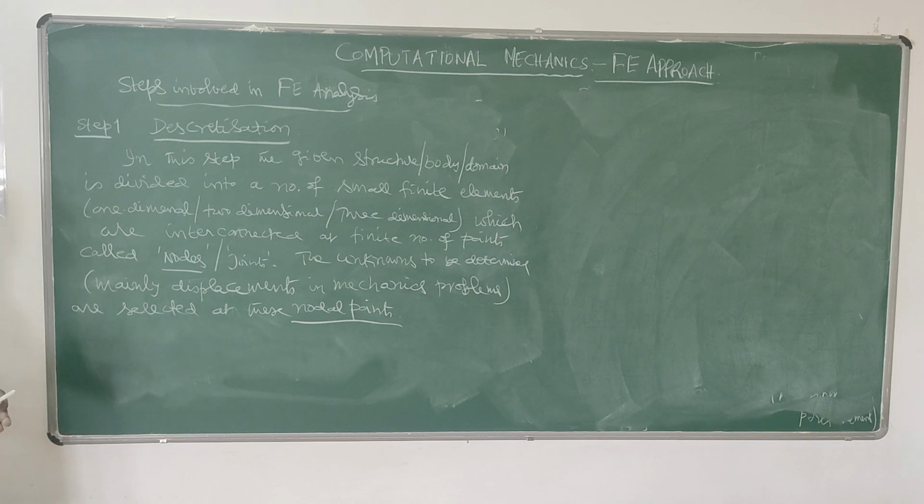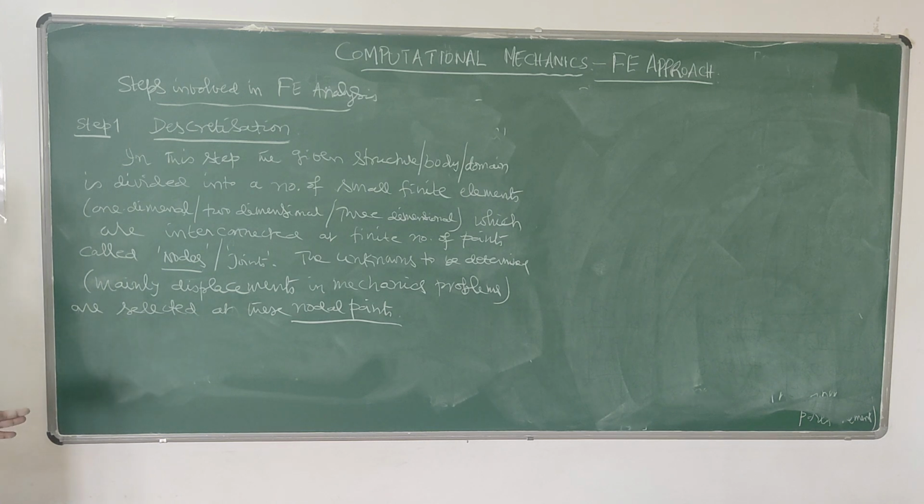In the rotation matrix also, you have seen the elements becoming zero. So in this stiffness matrix, if you can form a band above which all elements are zero, those elements you can just ignore and take only the elements which exist within the band, that is a banded matrix.